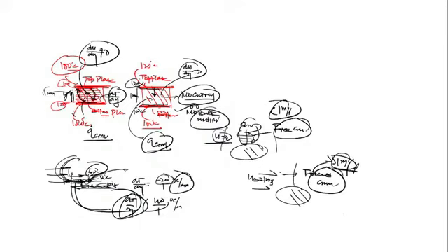But either free or forced, always on the wall where the fluid is stagnant, the heat transfer is via conduction only. Because even if motion is there, either free or forced, due to the no-slip condition the fluid on the wall is always stationary. Then on the wall the heat transfer is via conduction only, and by the fluid motion we are increasing the temperature gradient. That's why the rate of heat transfer via conduction increases. Is this clear?